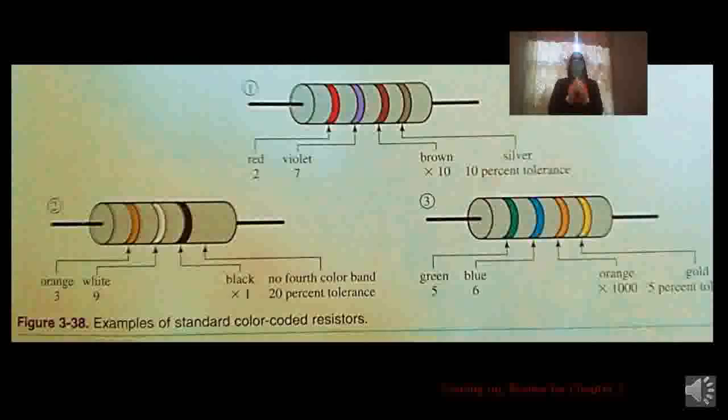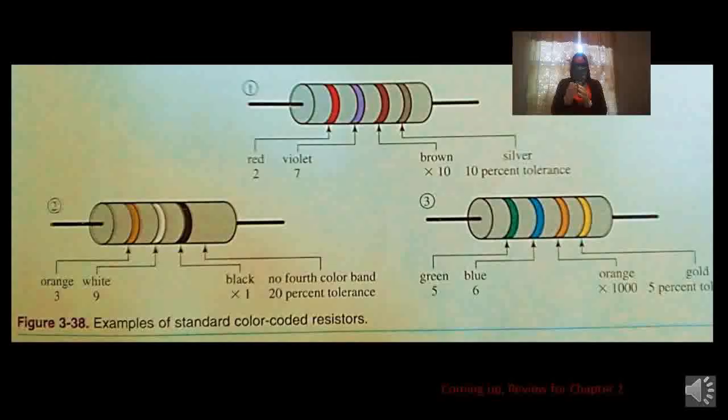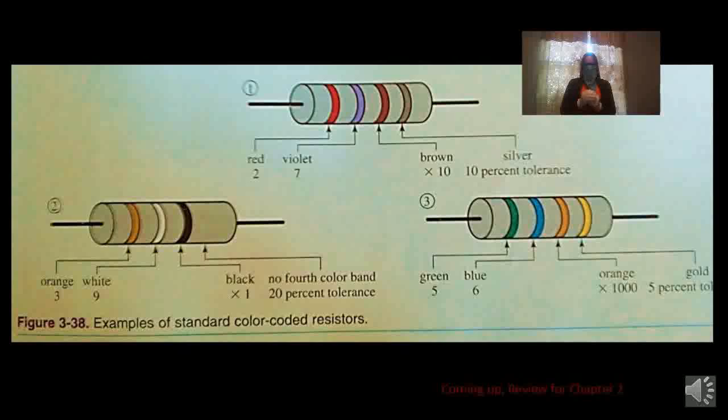The resistor tolerance is a reflection of the precision of the resistor's value. If a 20 ohm resistor has a 10% tolerance, the resistor's value can vary by plus or minus 2 ohms. In this case, the resistor can have a true resistance value of 18 to 22 ohms. A fifth band is sometimes used to indicate resistor reliability or expected failure rate.